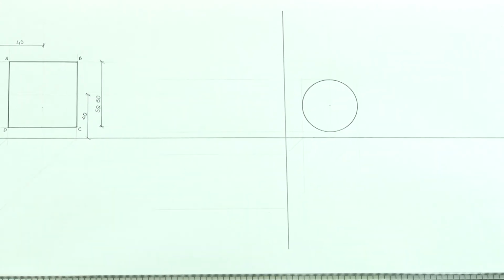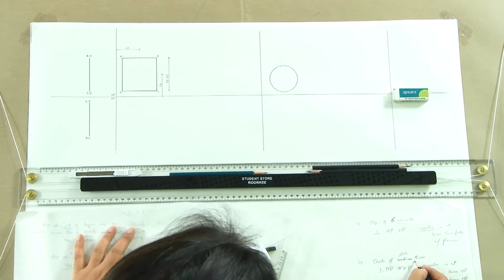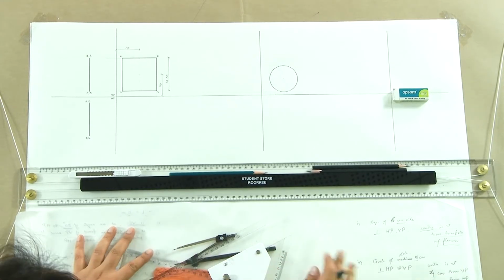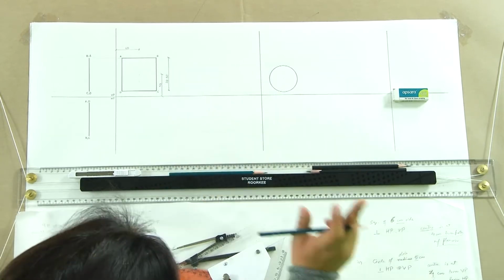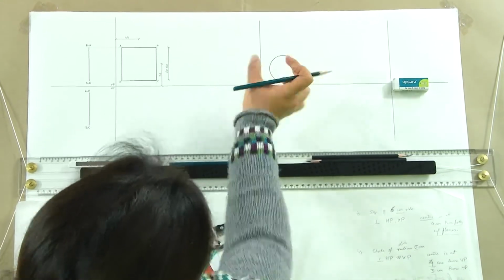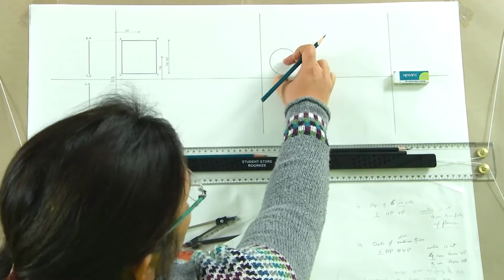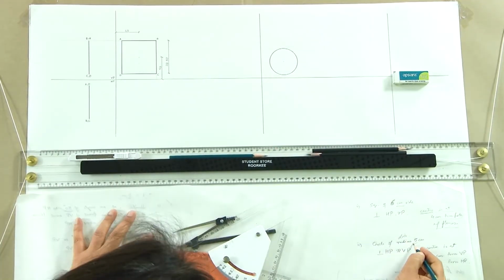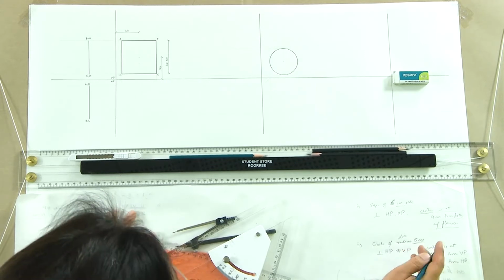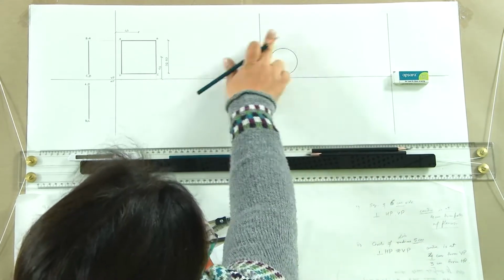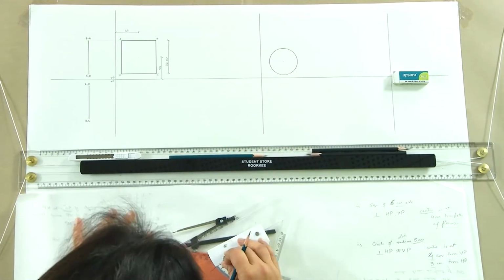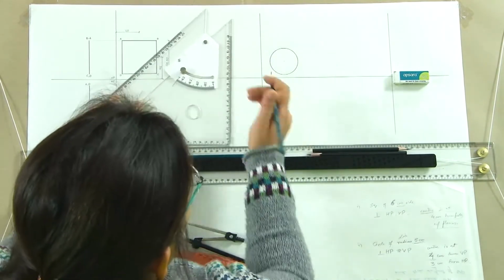If you follow the process that I am taking for drawing this, you will see that any dimension which is given here, I will be measuring only once on the sheet. So, I measured this 4 centimeter only once, I measured this 3 centimeter only once, and I have measured this diameter of 5 centimeter, which is radius of 2.5 centimeter only once. Once I have this dimension here, all other dimensions will be derived from the same drawing, which is how geometric construction should always work, right.